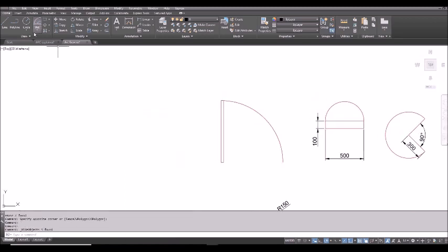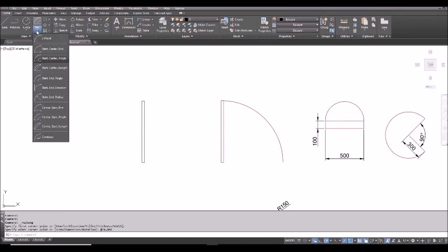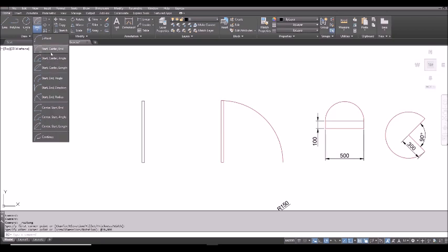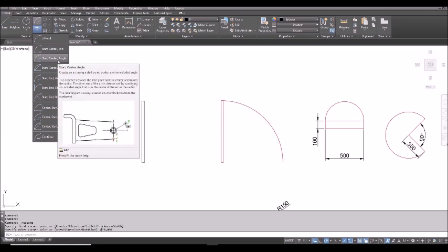Here, another door. This time open 90 degree. So click the rectangle 30, 800. And then again, I'm using start point, center point, angle because I know these three pieces of information. Is it possible to use other methods? I think so. It's just that in this situation, I think this one is good. So this is an exercise for you to use other methods.